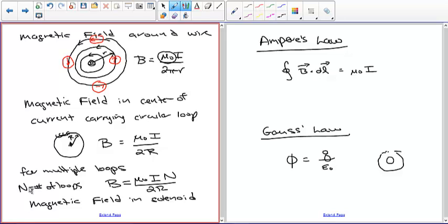And one thing you'll notice, so here's one that goes inside the other, and this one has much heavier wire. So this has fewer loops. This one has more loops, but the wire's smaller. If you use the same wire here, then this one's going to have a lot more current. If you put a certain voltage across these terminals, the current through this thing is going to be a lot higher because the wire's fatter, the resistance is less, and here the resistance is more because the wire's small.